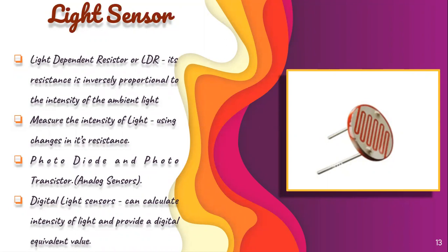Next is photodiodes. Photodiodes are another type of light sensor, but instead of using the change in the resistance like LDR, it's more complex, responding to light by easily changing light into a flow of electric current. It is also called as photosensor. Next is phototransistors. The last sensor type is phototransistor. It can be described as photodiode plus amplifier. With the added amplification, light sensitivity is far better on the phototransistors. Light sensors are commonly used in consumer electronics, automobiles, phone, gadgets, and agricultural usages.